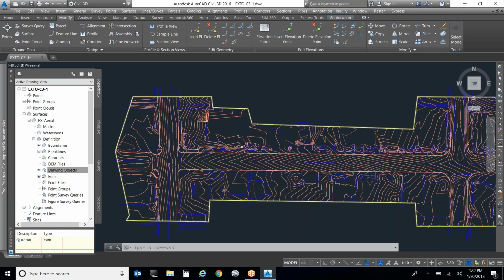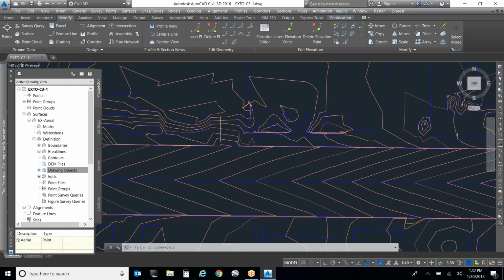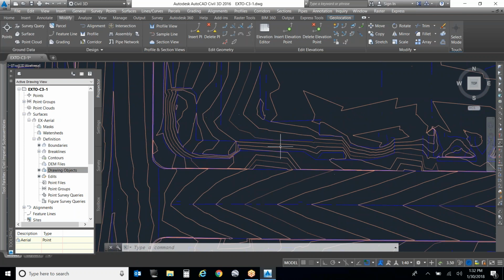Okay, so when you have something that tight, you can kind of see where the information is. You can see this is a driveway. In certain cases, Philip, you may not need that information to be part of your surface. You can just use the elevation from the point itself. If you do need to add it to the surface, we would need to talk a little bit about that, because you can't just add a random point and expect your surface to behave.